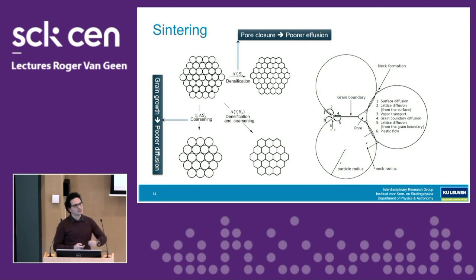But what is quite interesting to see, and I did not know that before I started having a student work on it, those two processes, they actually are enhanced for nanomaterials. If you have a very, very good nanomaterial where all your grains are perfectly the same size, it is going to be the best way for you to go to full densification. So actually, when people say, go to a nanomaterial, the consequence is that you accelerate the sintering. And they've typically been observed to perform poorer than the micrometer scale targets. Or maybe they start well and they degrade very fast, much faster.